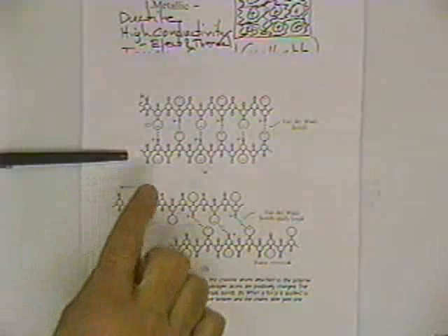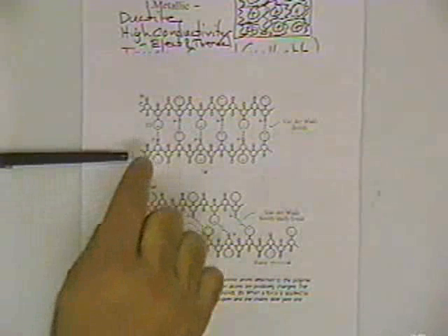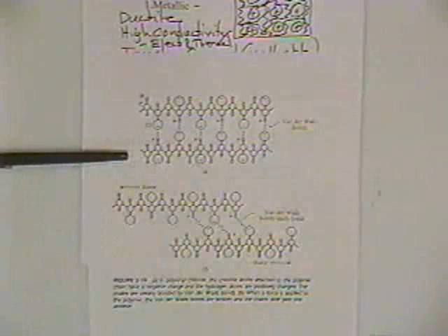Now, in polymers, the molecules are very long relative to metals and ionic and ceramic materials. And so lots of little secondary bonding can contribute to the strengthening characteristics. So individually it's negligible. Sum total, it makes a contribution to the mechanical behavior of polymeric materials.